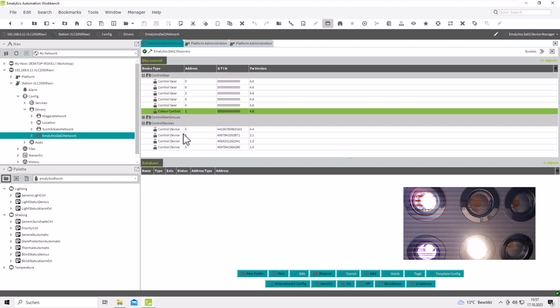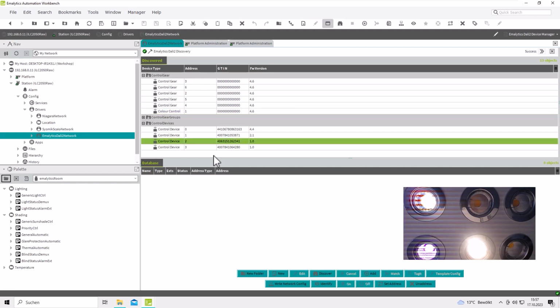And all sensors I know so far, they have a little LED implemented, and I can go to the sensor and push the identify button here. You see here also the on and off command. They are not able to push because, yes, all DALI 2 devices have the identify. So sensors are just DALI 2.